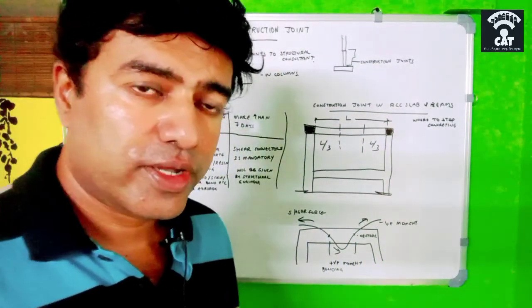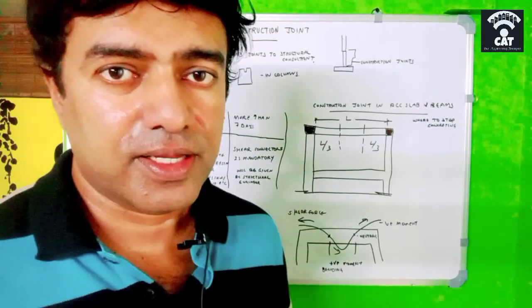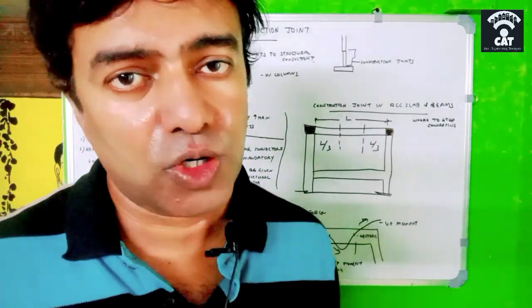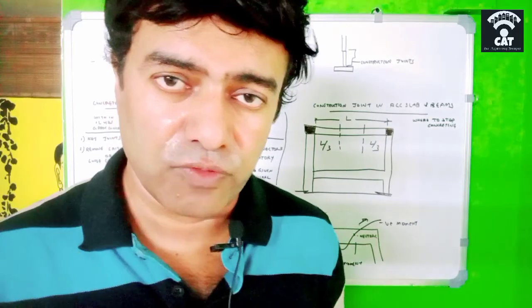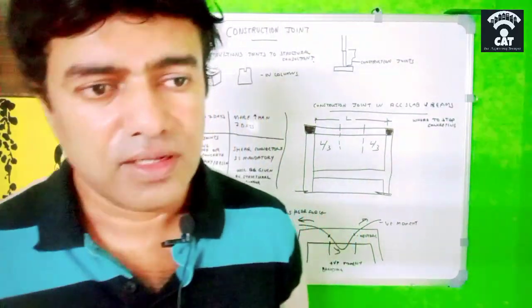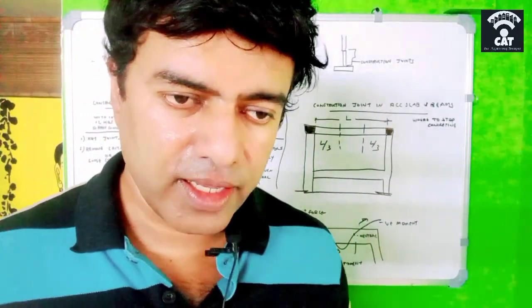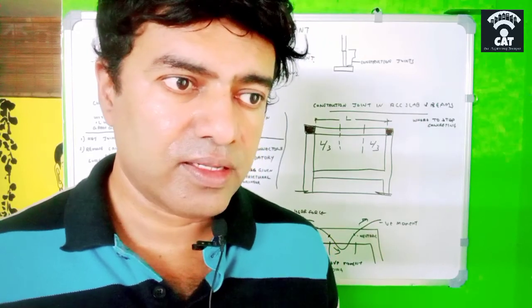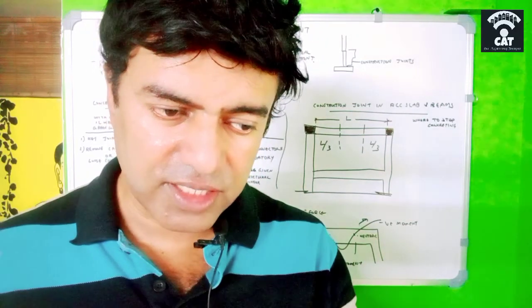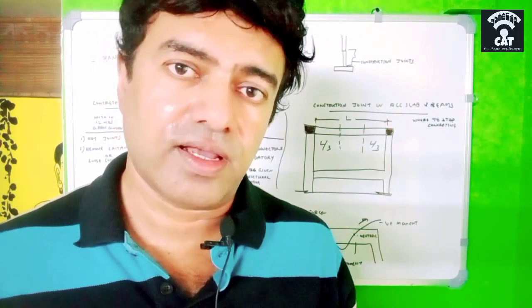These construction joints, as we know, can happen at any time, intentionally or non-intentionally. Intentionally, like I said in the before video, if it is a weekend or a holiday which we know prior, we can stop at a particular designed area or design point where it should end.